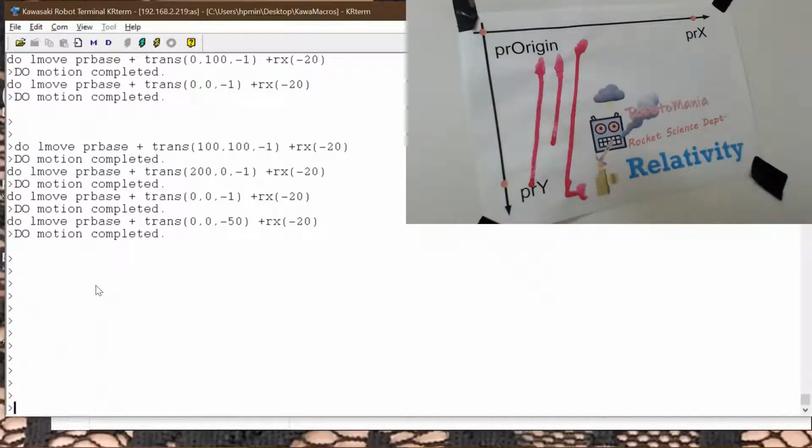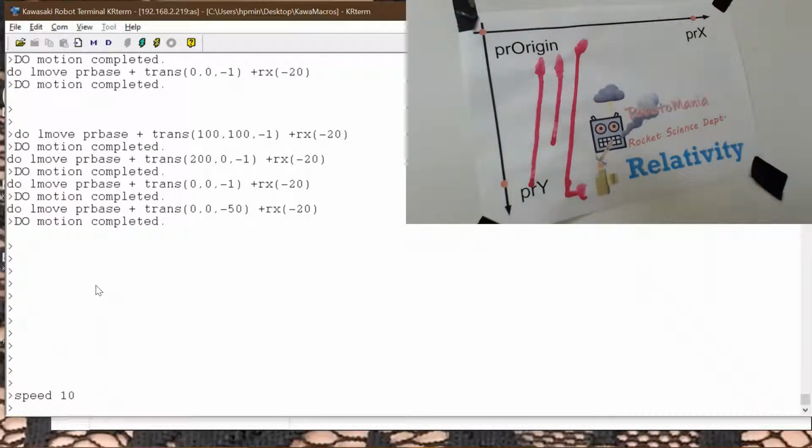Whenever I hit the enter key on my keyboard, I make sure to have my left hand firmly on the emergency stop switch. In case something goes bad, I would maybe have a chance to prevent a global crash. Obviously, it works better when we define a slower velocity.